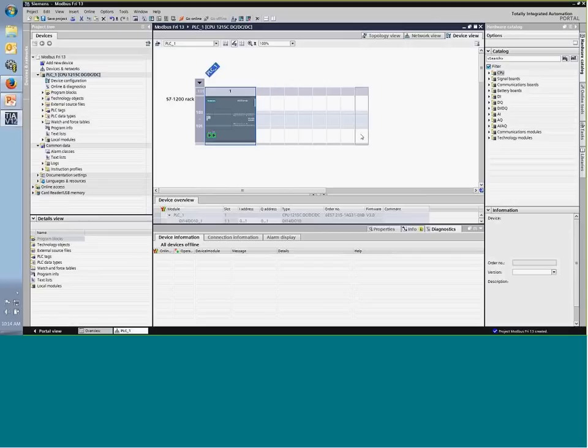Then you can see there is some space on the right side of this CPU. Also, a neat feature of the 1200 is that it's a standard DIN 35mm rail mount, so you don't need special racks for it. You can use regular DIN rail and just mount the CPU right on the DIN with other components. On the right side of the 1215, there's an option to add 8 different I/O modules.